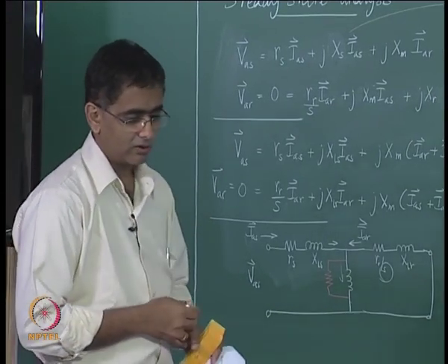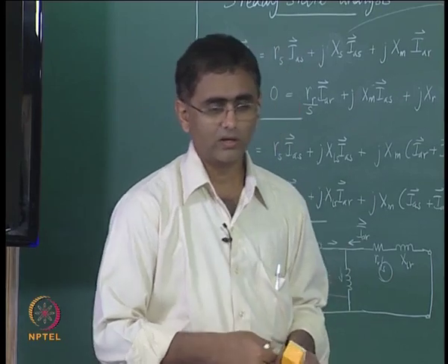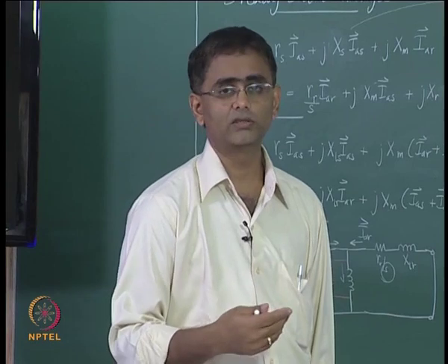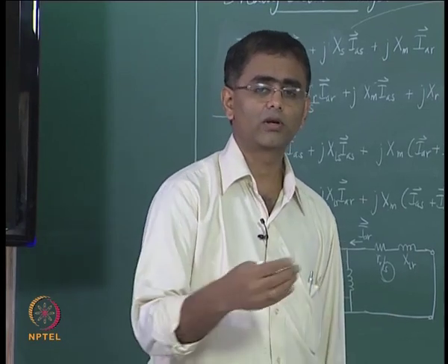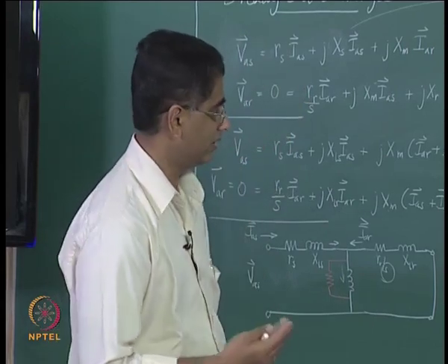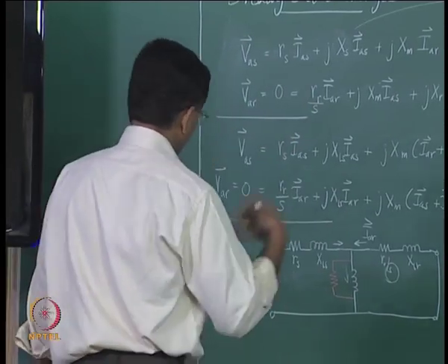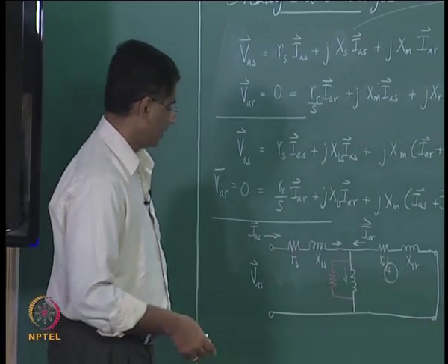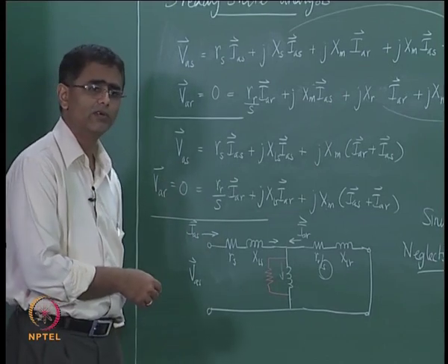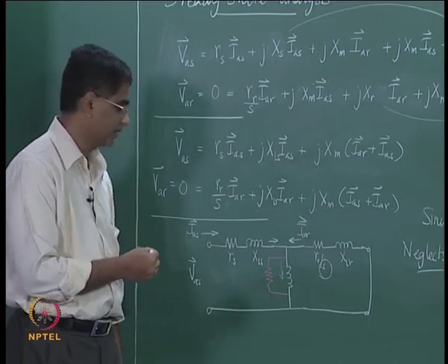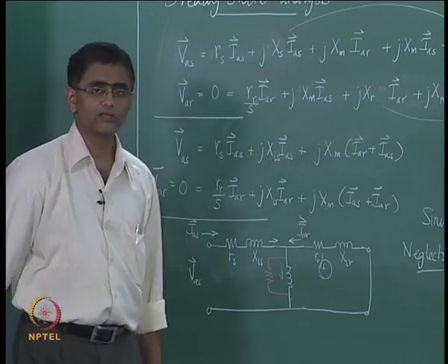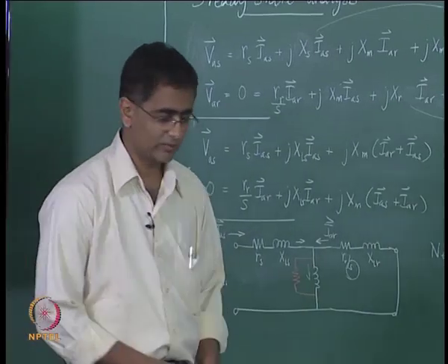Sometime later on in one of the lectures we will see a response, a solution of these equations done through a computer, to see what kind of responses one gets when the machine undergoes an acceleration or a deceleration, but that is for a later date. For now we have achieved our job of deducing the steady state equivalent circuit from this representation. This is for an induction machine, a 3-phase induction machine.